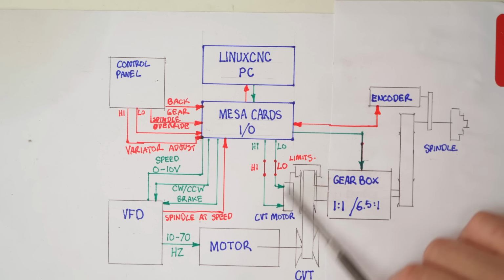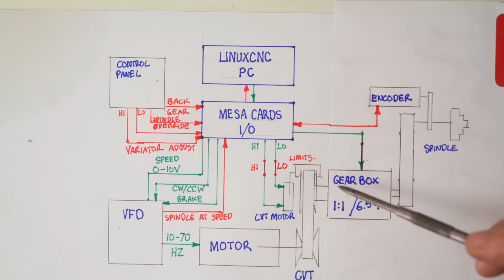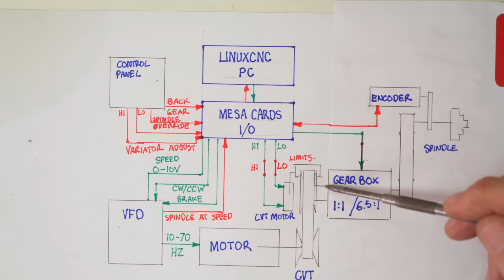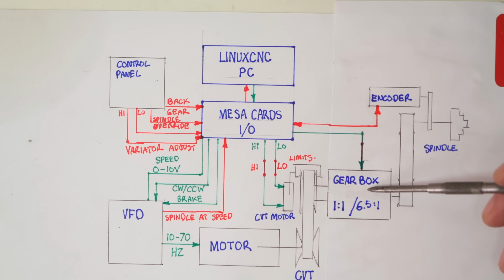But I already own these bits. I'd have to pay money to rip it out and change it. It would mean buying a big motor, a big VFD, and then making a whole bunch of mechanical parts to make the thing fit. The second issue I have with ripping it all out is the advantage of mechanical speed reduction is that you get an equivalent increase in torque.